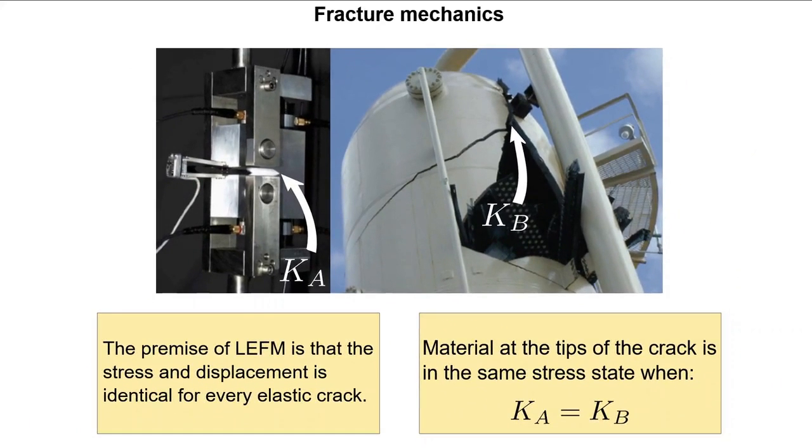The stress intensity factor K is a characterizing parameter that dictates the elastic field that surrounds a crack tip. And if it exceeds the fracture toughness, then somebody's going to have a bad afternoon. More specifically, KIC is the critical value of KI, the stress intensity factor for opening, which will cause the material to break under plane strain conditions. Like other properties of metallic materials, it will change with temperature and anything else that causes a material to exhibit diminished ductility.